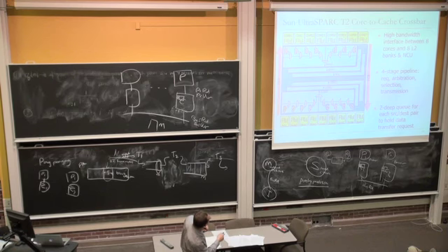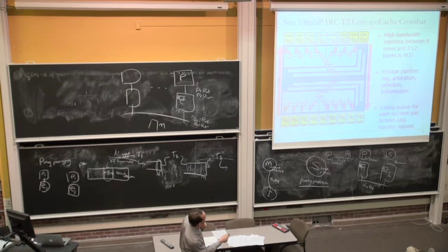And this is the non-cacheable unit, if I remember correctly. So this is essentially the crossbar. It's not shown the same way I've shown it, but this shows the conflicting destination. If all of the cores want to send a message to bank 0, this is how arbitration is done. And that's the arbitration that they talk about. It's a 4-stage pipeline for arbitration, essentially. You request, arbitration happens, the arbiter selects one source, for bank 0 in this case, and the transmission happens.